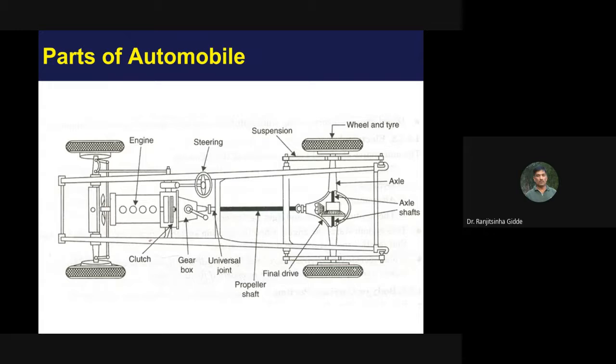Along with those wheels, there is a steering mechanism that we are going to see in detail. This is the steering. This is the steering gearbox, where this rotary motion is converted into oscillatory or to-and-fro motion of this arm, and we can have motion in an arc for this vertical spindle.